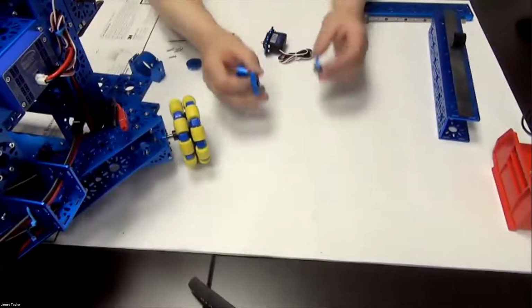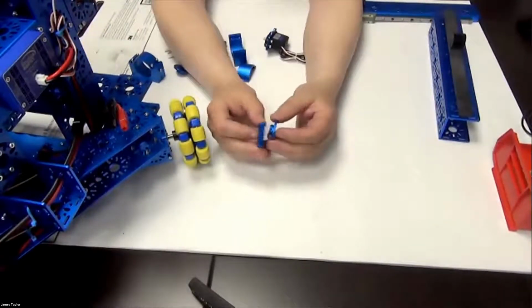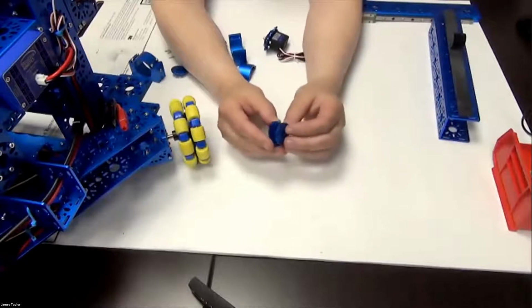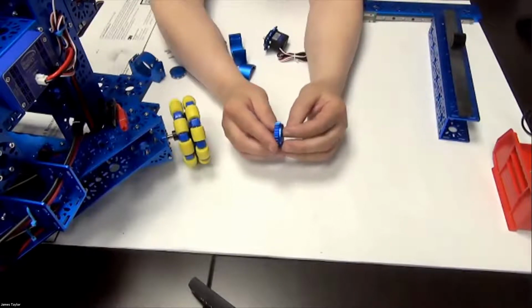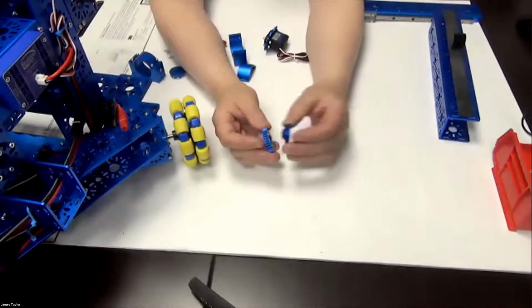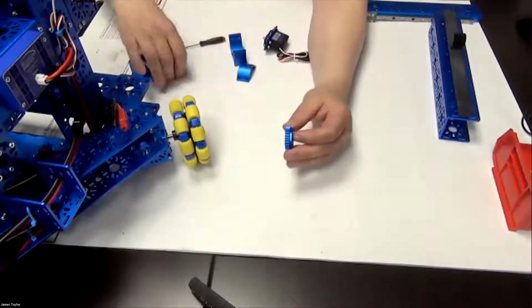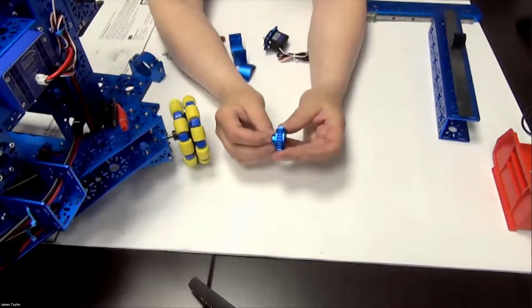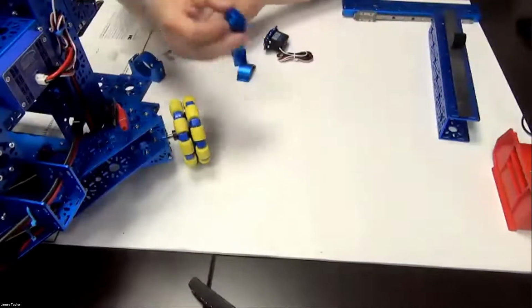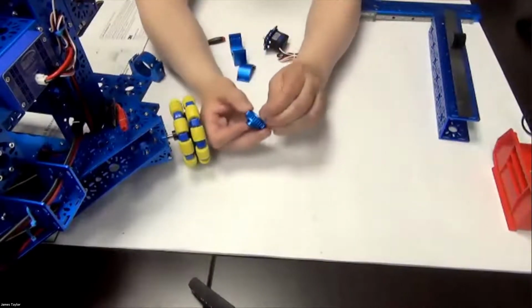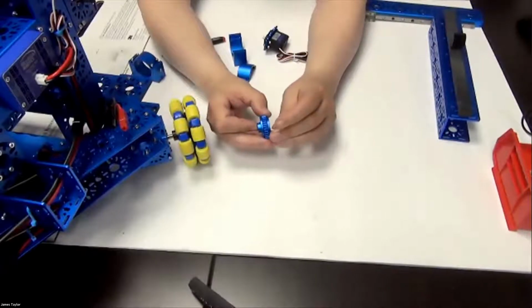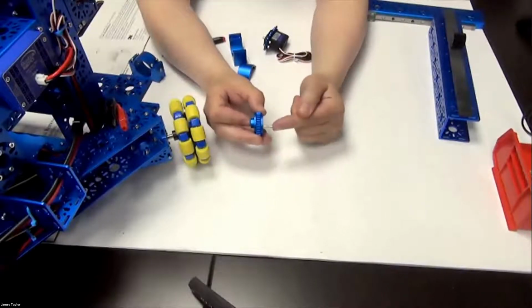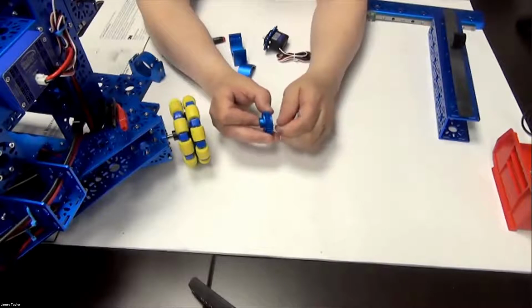So what we actually did with the gears was we took one gear, we took one shaft hub, and we put the shaft hub through in the reverse direction that I told you. We have another shaft hub on the outside of the gear. And then we actually threaded through the first shaft hub and through the hole a 12mm socket-headed cap screw.